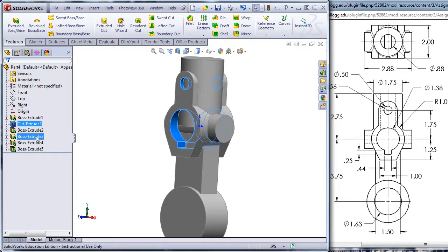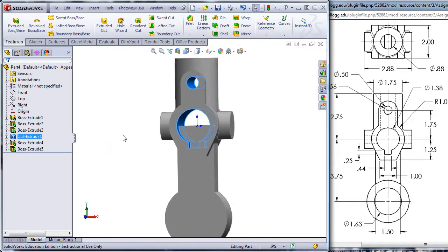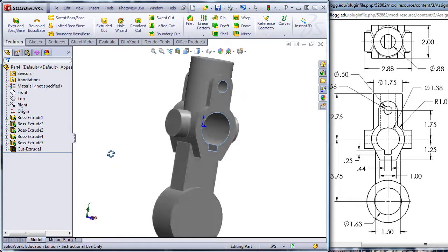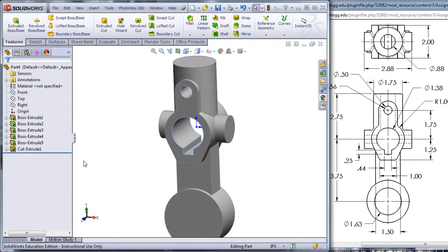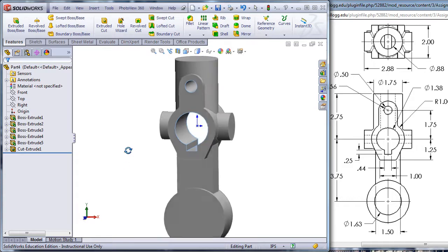So let's drop it right there, and you'll see that now I've gotten back part of the hole because it happened after these two extrudes, but still the rectangle's in the way. So I'm going to go ahead and pull that down all the way to the bottom. So the cut is now the last thing, and you can see that my model has healed. Okay. So that's how historical modeling works, in that you can sometimes change the sequence of history here.